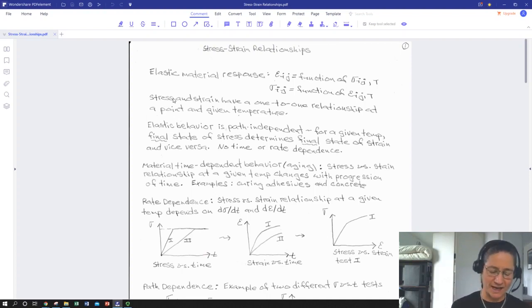Okay, so what's non-elastic? Time-dependent behavior. There's some materials whose entire array of mechanical properties change with time and or with temperature, or a combination of time and temperature. This is usually due to certain chemical reactions and chemical processes occurring within the material that are both time and temperature dependent. Two typical ones that you might see in practice are curing adhesives and curing concrete.